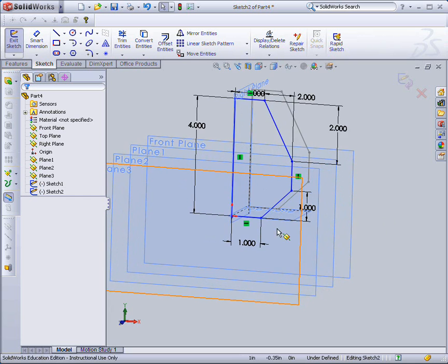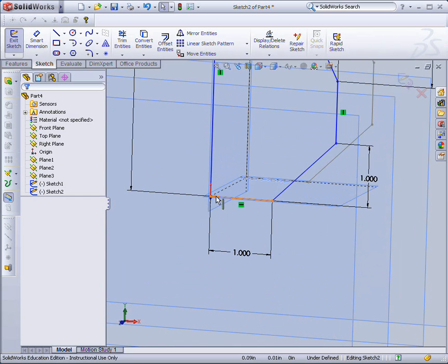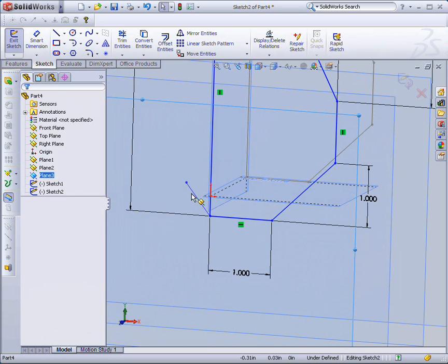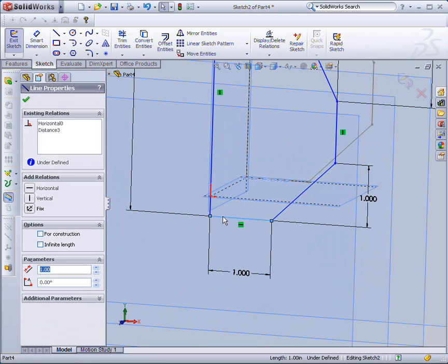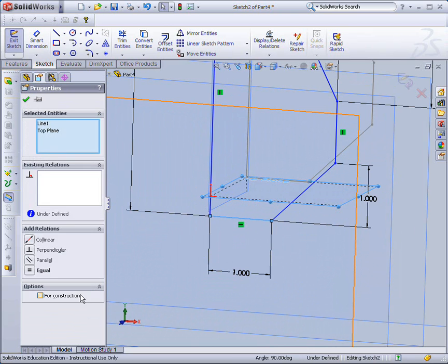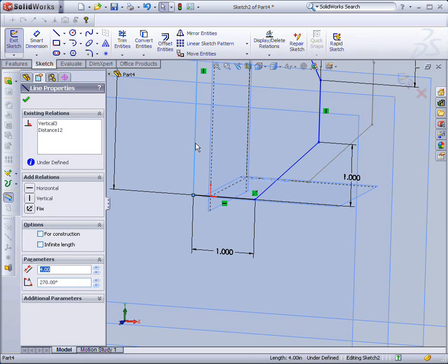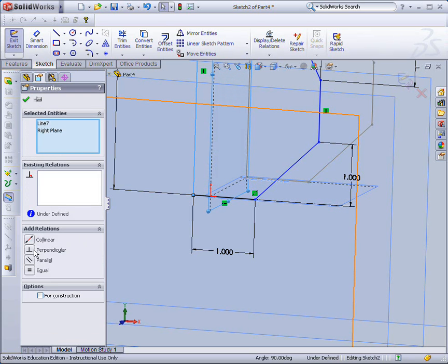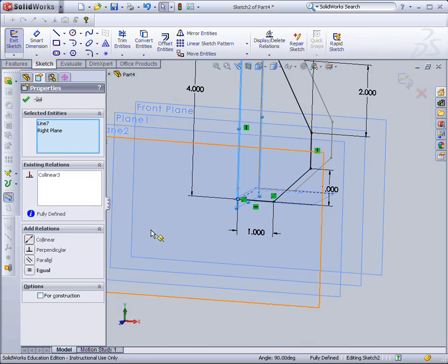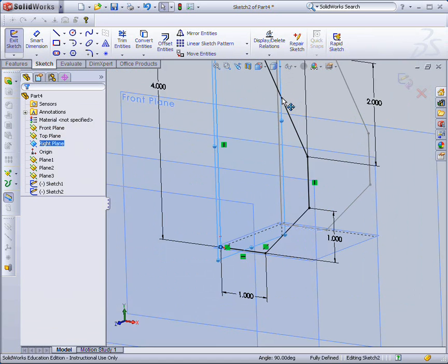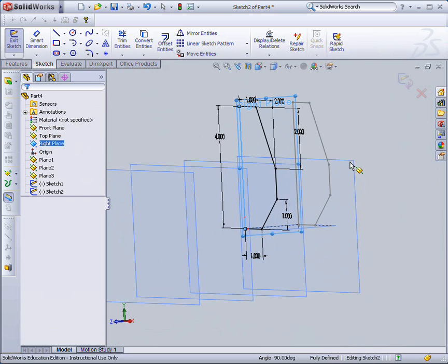You can see everything's blue right now. So we're going to drag some of these around. Ooh, that's interesting. Put that extra line in there. So this one we're going to select there, make those collinear, and then we'll do the same with this line here. And if you notice, our whole sketch is constrained now. However, we have some slightly different dimensions.